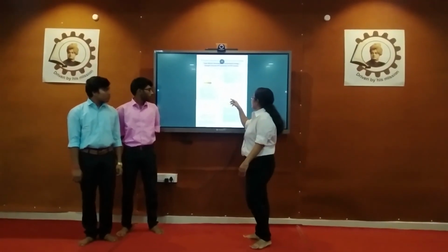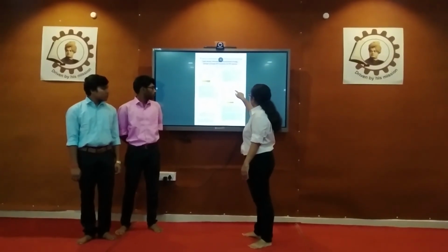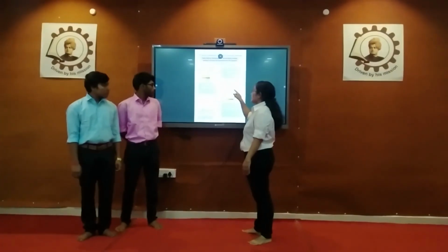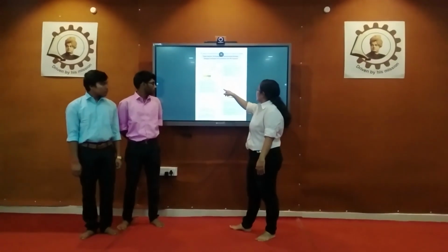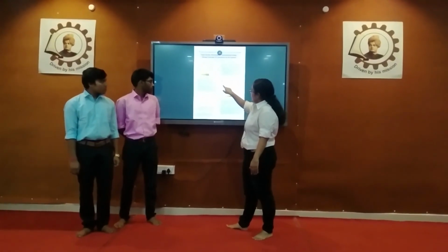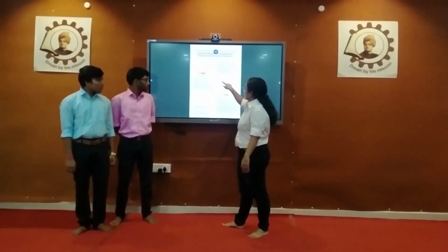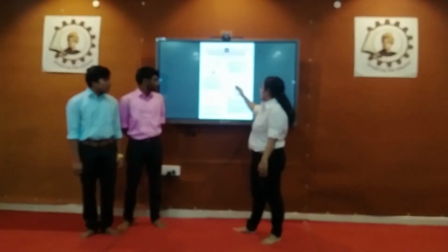In this circuit diagram, if we take stage 5, we can see that if we switch on P1, S1 and P3, there will be no voltage on load. But in stage 4, P1, S3 and P3 are on and we are getting all the input voltage in the output load.